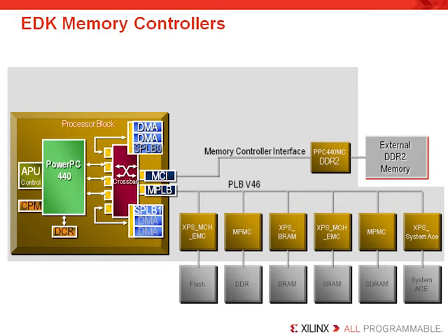So from left to right in the diagram, the first is the external memory controller or EMC component attached to an off-chip flash device. The next is the multi-port memory controller or MPMC component, and that's attached to an off-chip DDR memory in this case. The next is a block RAM memory controller attached to on-chip block RAMs.